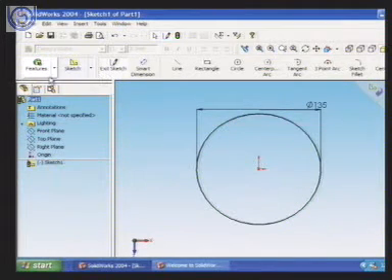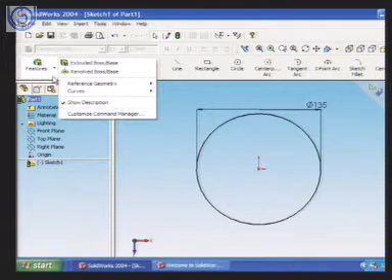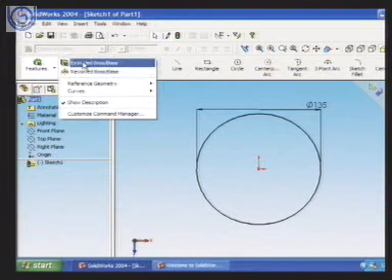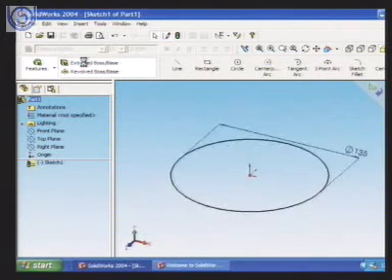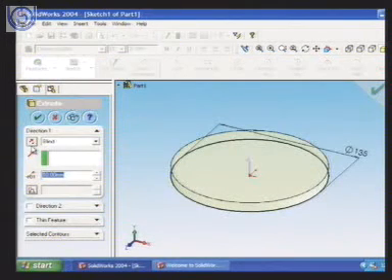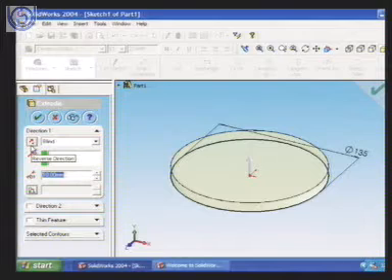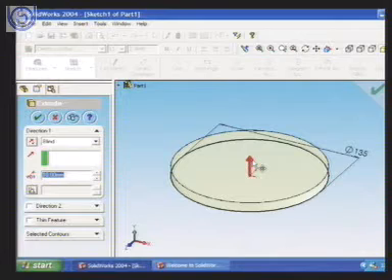I will show you how. Now this is a sketch. It is no more 3-dimensional, it is 2-dimensional. Now I want to change this entity to 3-dimensional. So what will I do? Here we have the option extrude boss. So I will extrude this entity. I will say extrude. Okay. Now this is giving us the direction. If this is the direction, it is extruding in this direction. You can see the arrow. So it means origin is here.